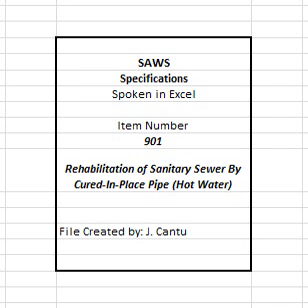The required structural wall thickness shall be based as a minimum on the physical properties listed above, the design equations in ASTM F1216, Appendix X1, as referenced by ASTM F2019, and the following design parameters. 1. Pipe condition, fully deteriorated. 2. Minimum design safety factor, 2.0.